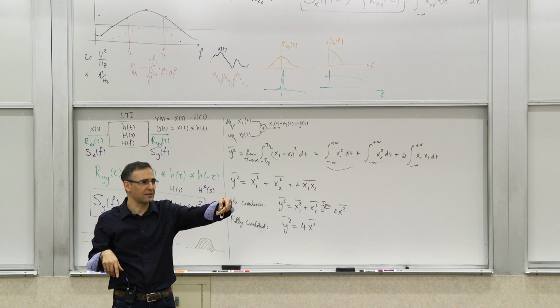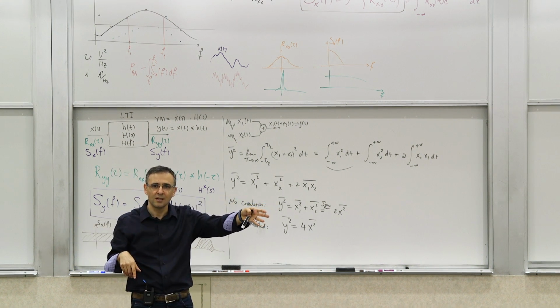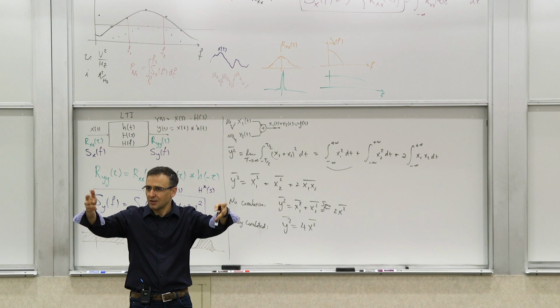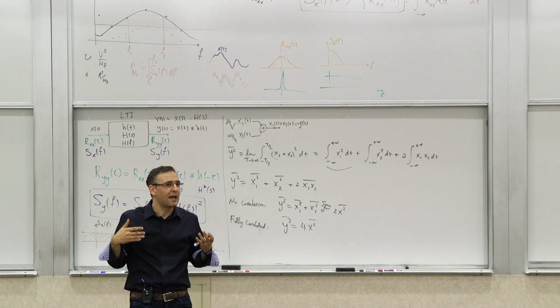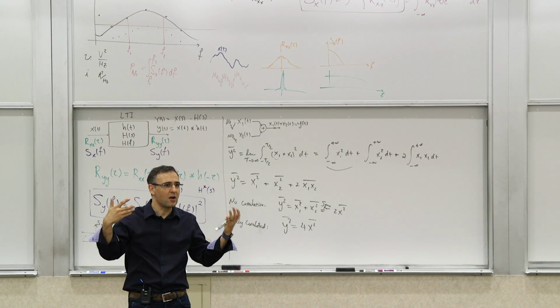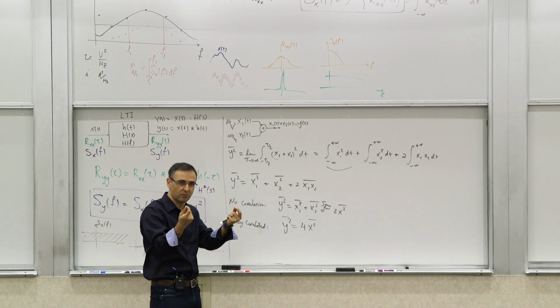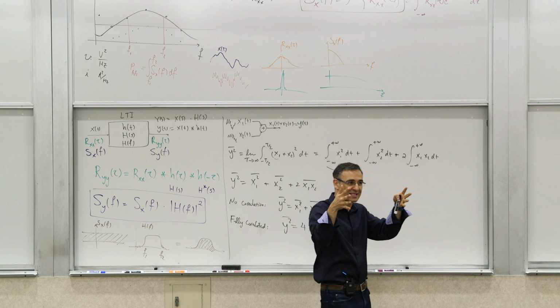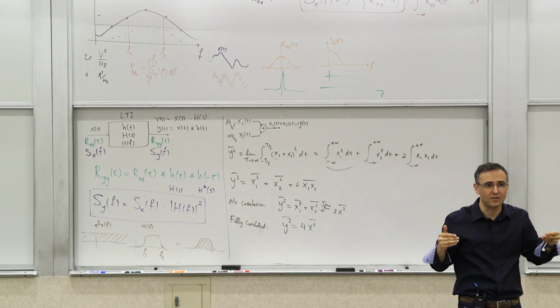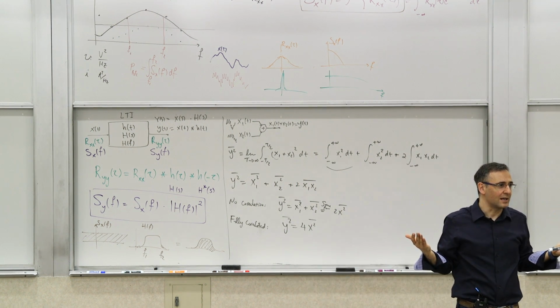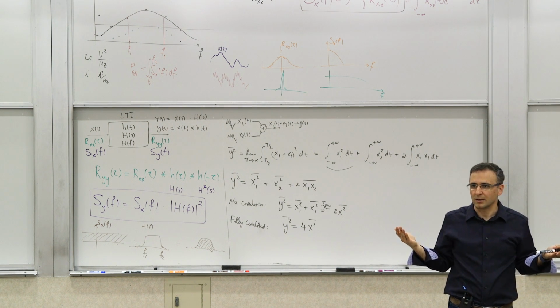Their behavior is not affected by the electrons moving in the other one. So each one of them has independent movements. As a result, they are generated in different physical locations by different physical groups of things. I mean, they may be the same phenomena, but different physical behavior. So they will be uncorrelated if you take two resistors by that argument.